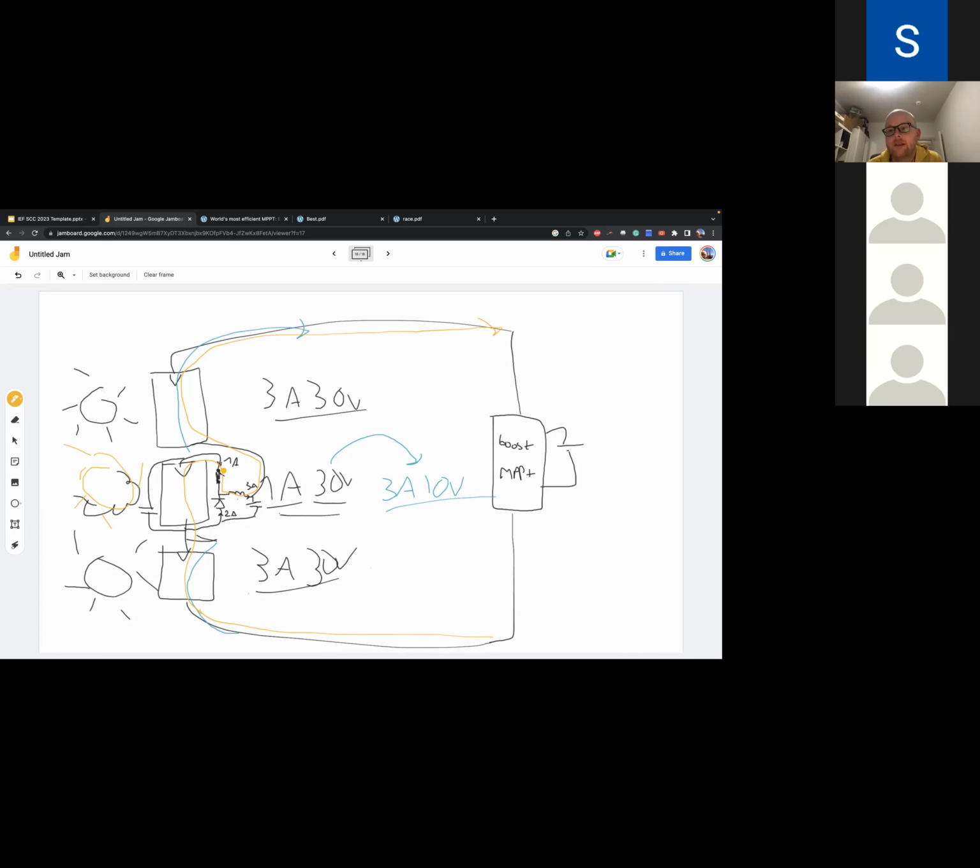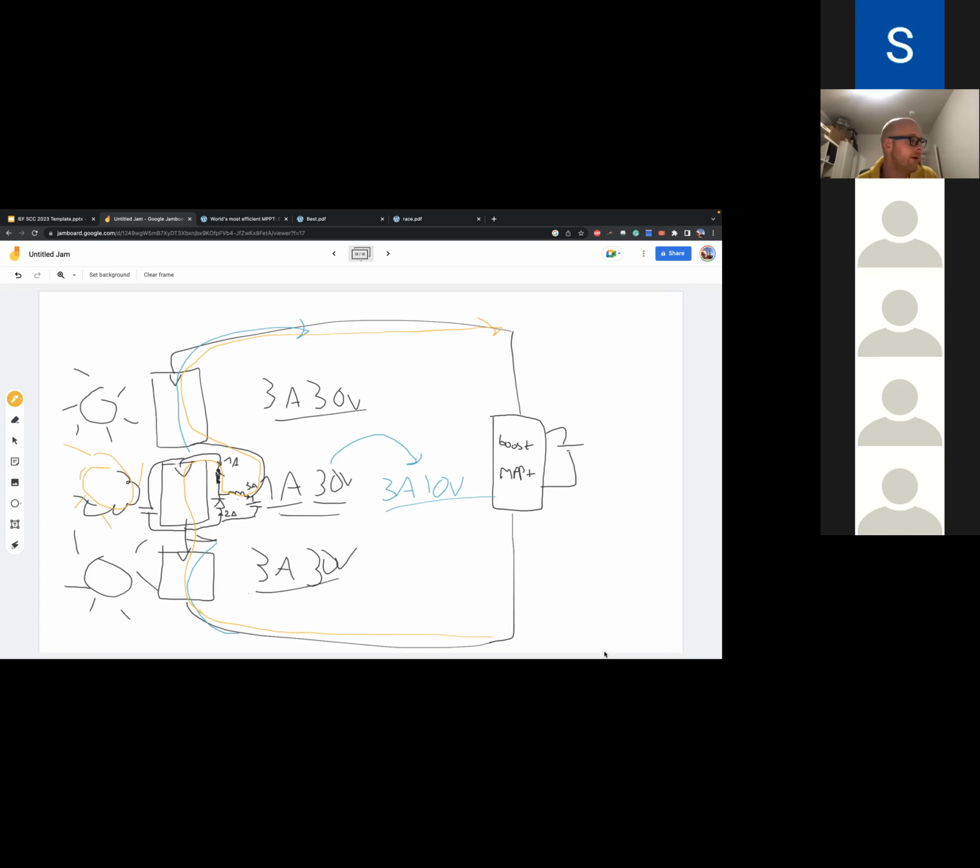But teams are always like, oh, we're just consuming extra energy and adding extra weight by connecting this fancy monitoring system. But really, that's step 1 to winning a lot. First you lose a little bit by making a good data acquisition system. It costs a lot of time and a little bit of energy and weight, and then you realize that you might be able to win 100 watts somewhere. You should measure what's going on first.